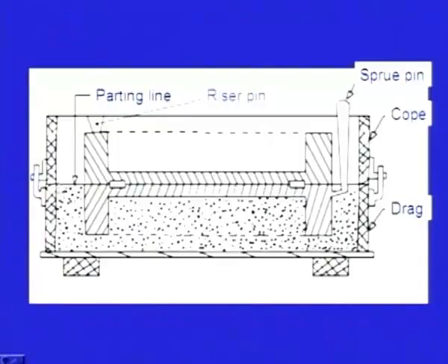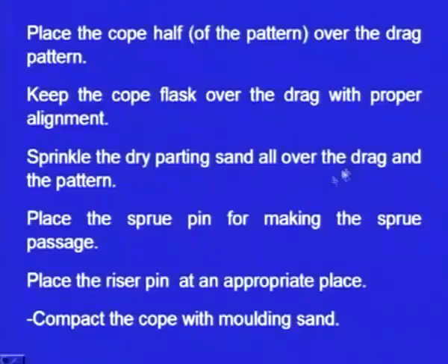The pattern should be withdrawn easily, and the sand of the cope box should not be sticking to the molding sand of the drag box. For that purpose, we are sprinkling dry parting sand starting from here and here, here, here. We will be sprinkling the dry parting sand.